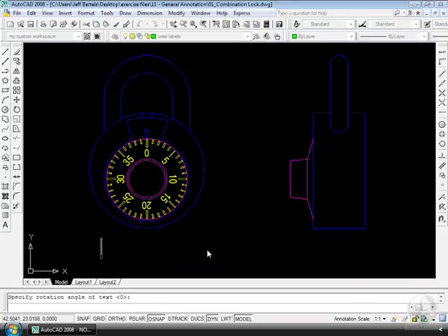Okay, I've got a flashing cursor. I can type. Let me type in front, space, view, and to get out of the text command, now that I'm done, I'm going to hit my enter key twice. Enter, enter to clear the command.